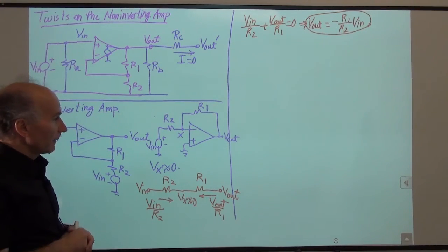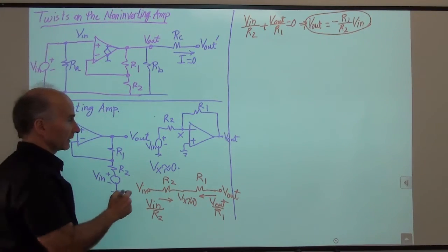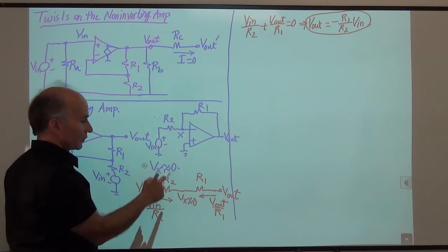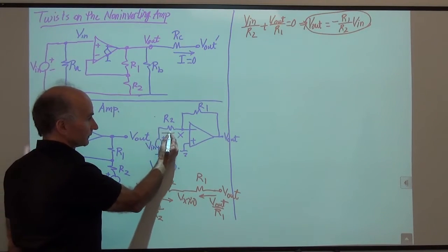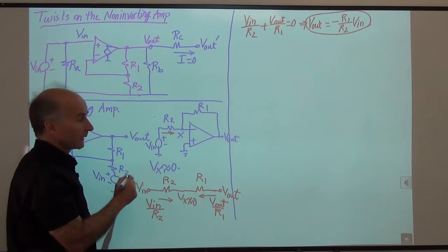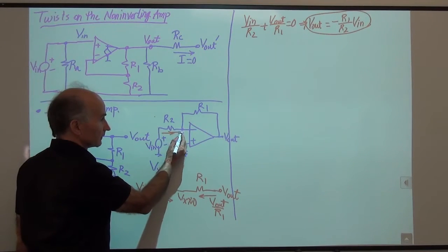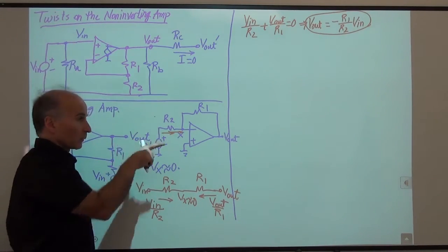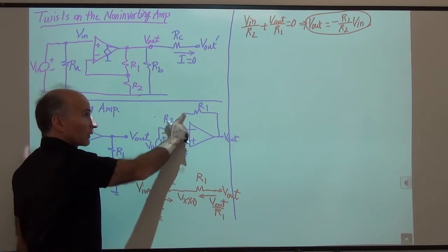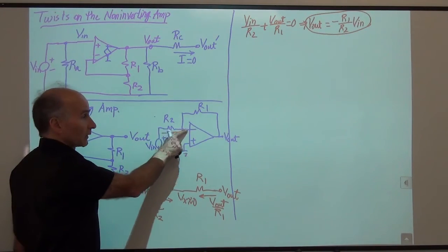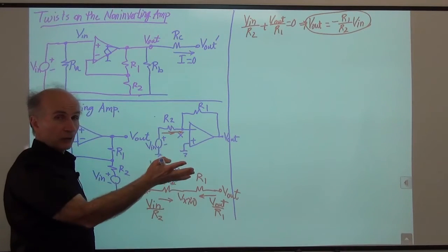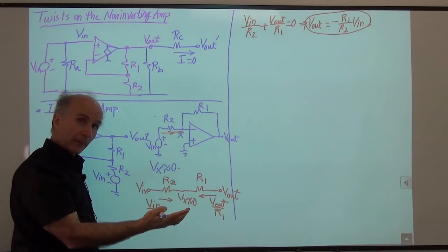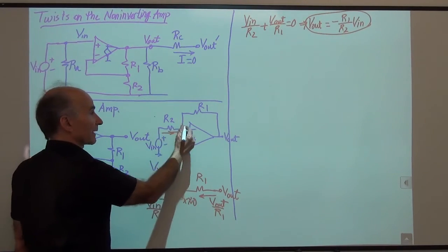All right. From another perspective, what's happening is that this voltage generates a current through R2. That current comes in here. And where can it go? It sees two wires, one going to the op-amp and one going to R1. Now the wire going to the op-amp does not draw any current. That was our assumption about op-amps. So all that is left is this way.